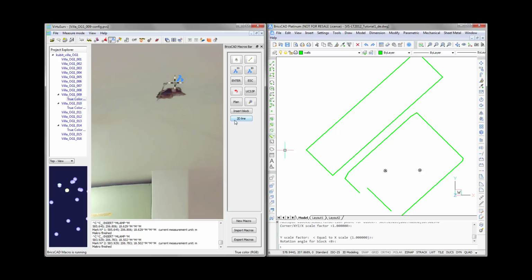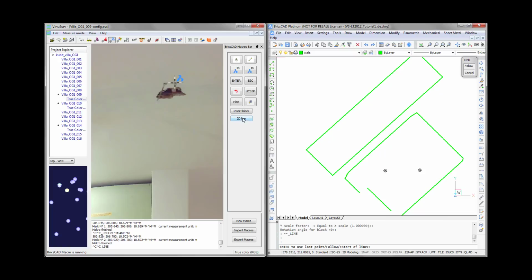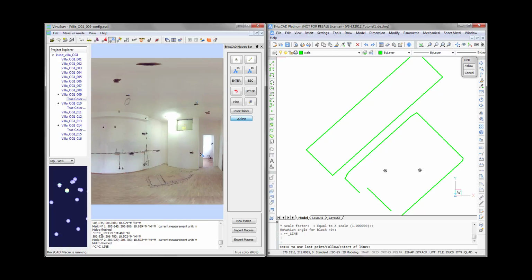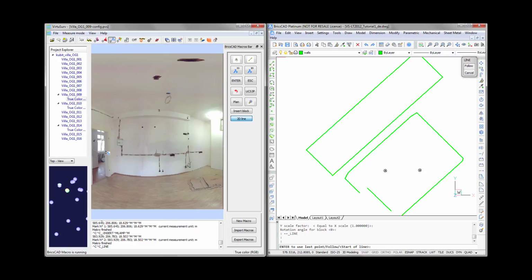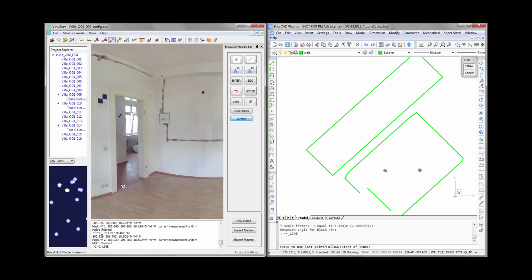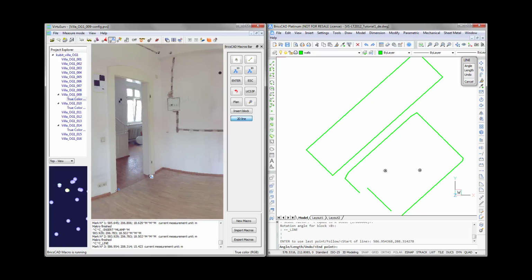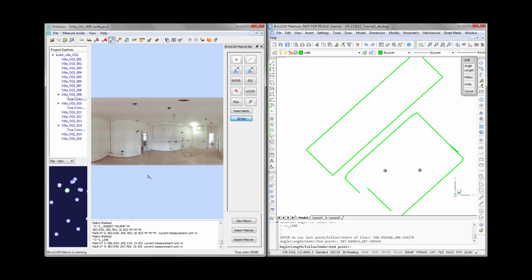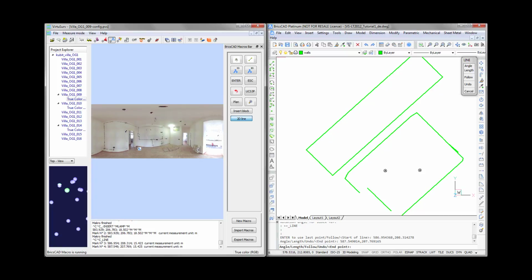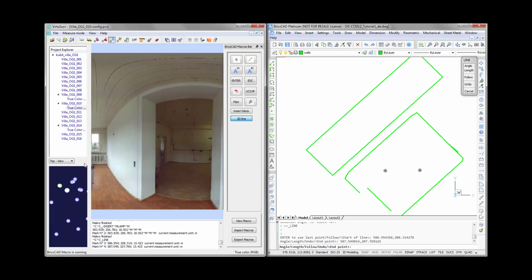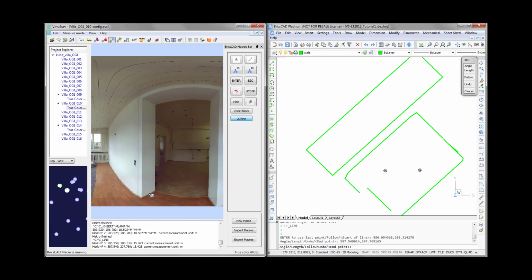So if I want to draw the doors later on, I will just get me some 2D lines which I can use later to insert door symbols using my native BricsCAD commands over here, and another door over here. Or let me switch to the neighboring room scan, because we have the door much nicer in here.